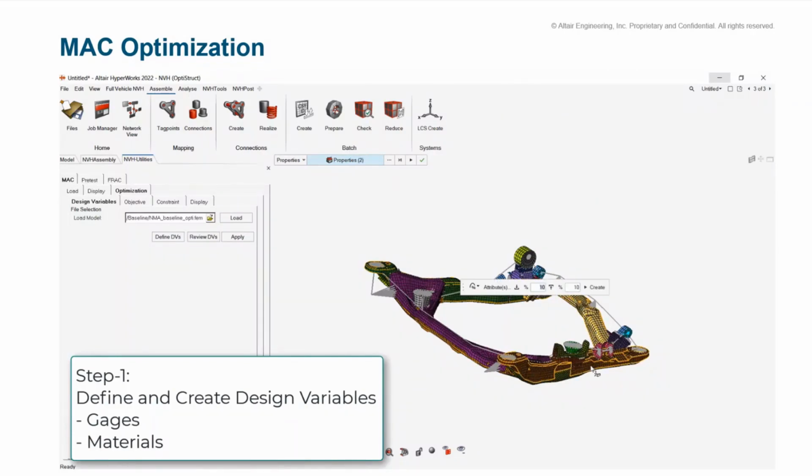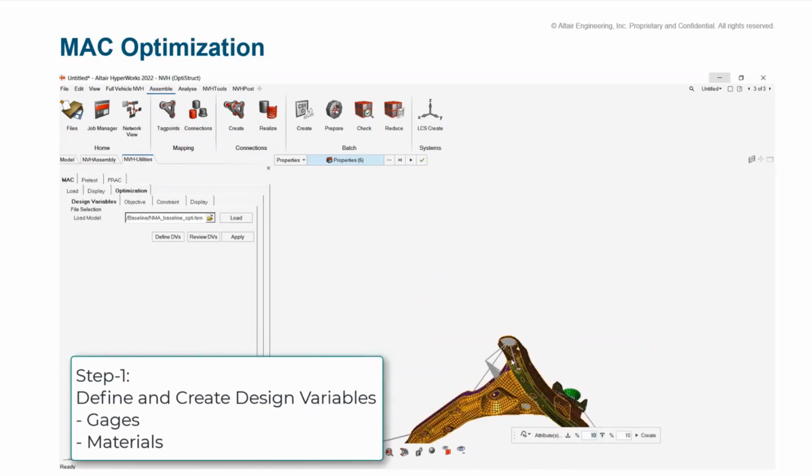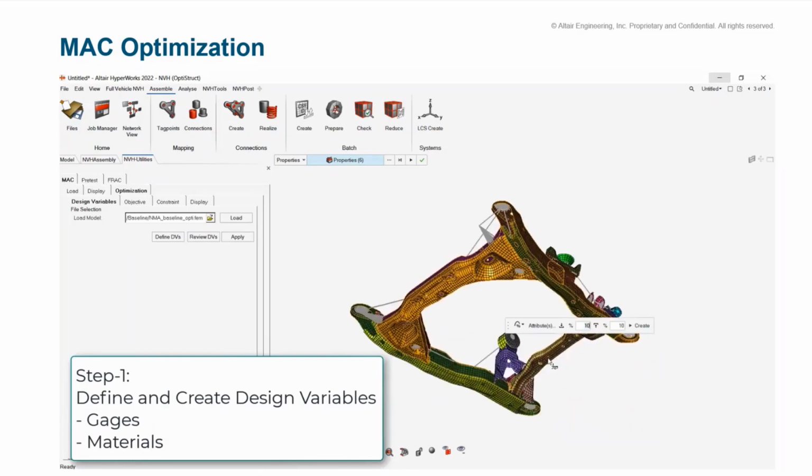Here, I'm selecting some properties by selecting them from the screen. There is also a possibility to select all the properties from the advanced selector. So it is a typical guide bar, which you will see in the Unity framework. You can select your attributes. I am selecting now thickness and specifying my lower and upper bound. I'm selecting 10 plus minus 10% variation for thickness.